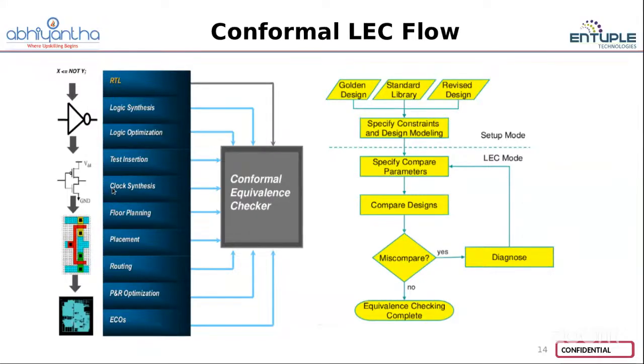Then you can switch over from the setup mode into the LEC mode. In this LEC mode, we specify the compare parameters, that is, what parameters you need to compare between your golden design and the revised design. Once your comparison is done, if the comparison points do not match, if it is mismatched, then we need to diagnose the mismatching points.